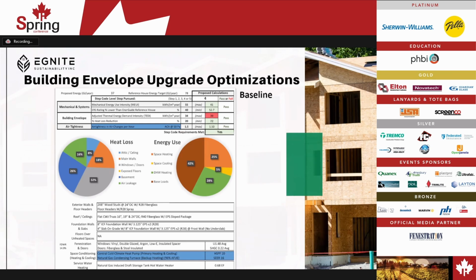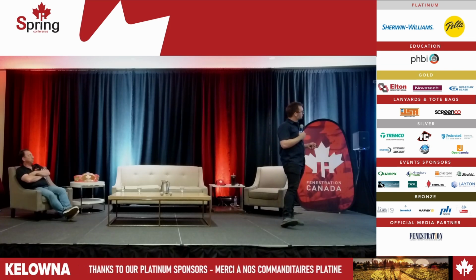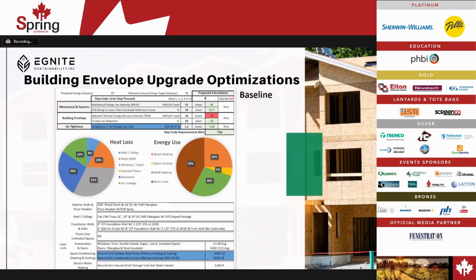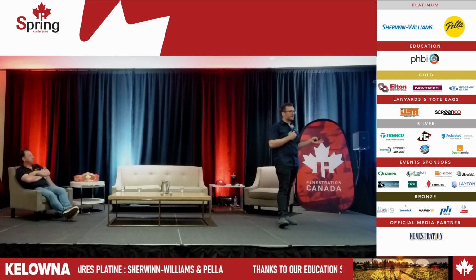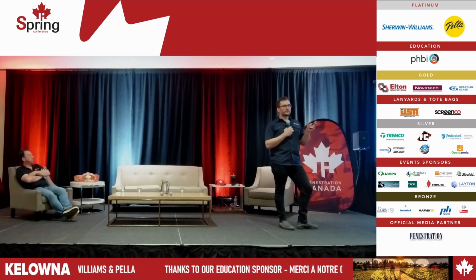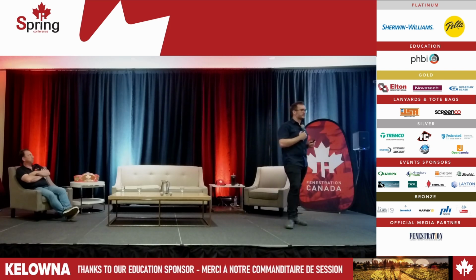So what we ended up doing was going through the integrated design process, running some different simulations with different wall assembly types and different levels of window performance, to see what we could do to get this project to step 5. With what this builder was already building, they were building with 2x8 walls, 16 inches on center with R28 fiberglass batts. They had already upgraded the basement walls with an ICF equivalent to an R28. And they were doing a dual fuel system: an air source heat pump and a backup natural gas furnace for their primary space heating and their cooling.